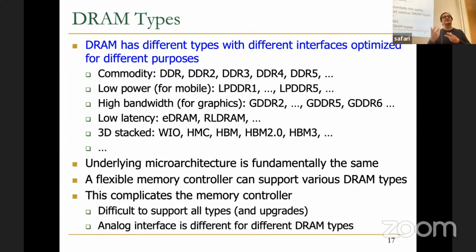Now, today, there are interfaces like Compute Express Link, where people are trying to communicate with the outside world with high bandwidth and low latency, in quotations, because it's not clear if that can be low latency. So you can actually be more flexible. Maybe you can send a request to memory through the Compute Express Link interface, and that goes to a memory controller chip, like it used to be in the past.